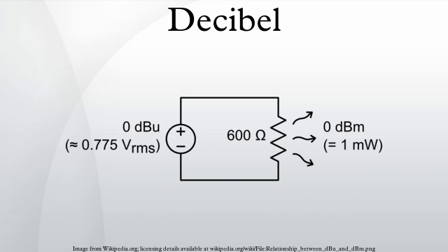Suffixes and reference values. Suffixes are commonly attached to the basic decibel unit in order to indicate the reference value against which the decibel measurement is taken. For example, dBm indicates power measurement relative to 1 milliwatt. In cases such as this, where the numerical value of the reference is explicitly and exactly stated, the decibel measurement is called an absolute measurement, in the sense that the exact value of the measured quantity can be recovered using the formula given earlier. If the numerical value of the reference is not explicitly stated, as in the decibel gain of an amplifier, then the decibel measurement is purely relative.